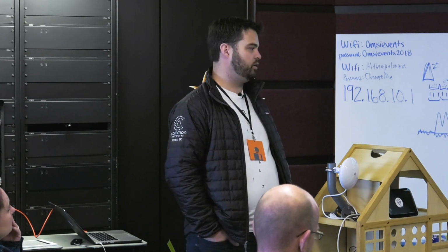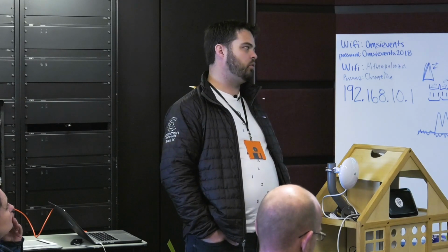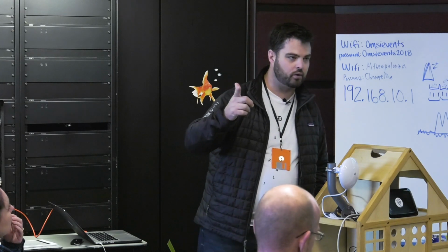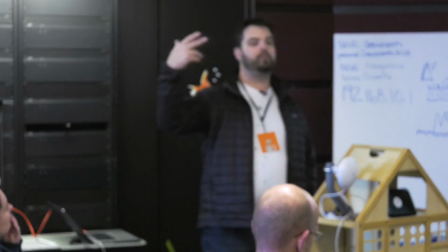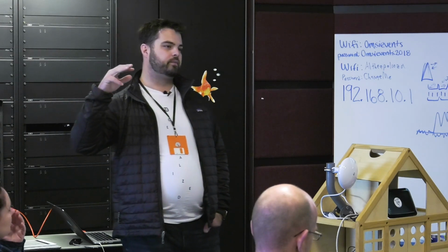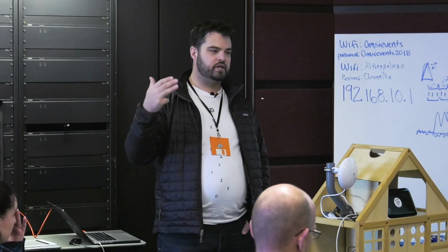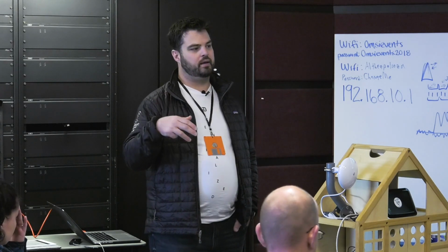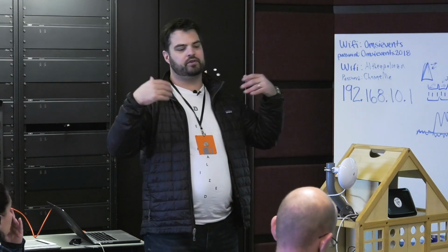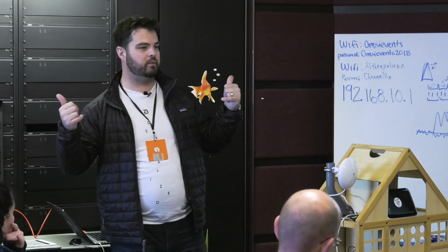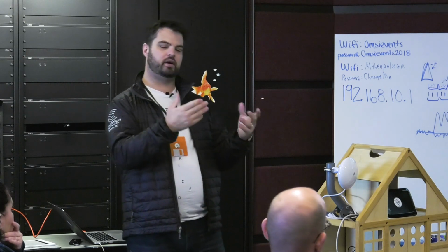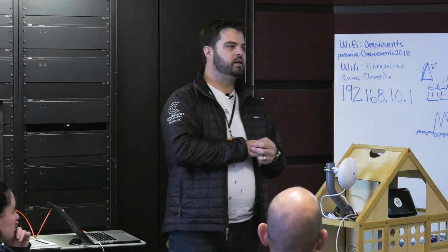The next step here is you fill out a tower application, and they're going to want to know everything you're going to put on the tower, all of the lines that you'll run to the tower, whether or not you want to use their battery backup or generator system if they have one, and how much power you'll be using, although you'll be paying for that directly. And they'll want to know everything about the antennas you put up, their size, their weight, the direction that they'll be aiming, what type of mounts you'll use on the tower. So they really are going to want a pretty thorough application.